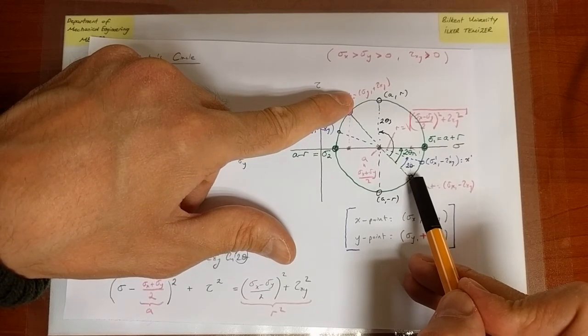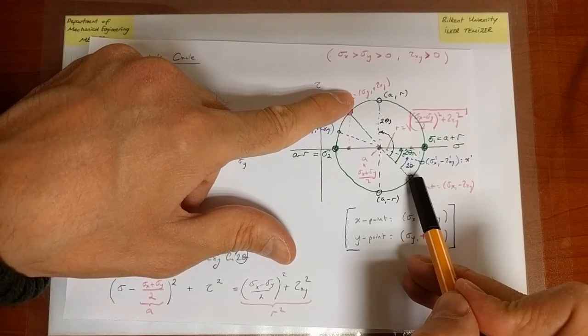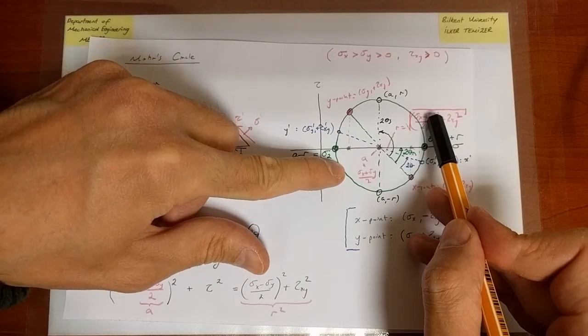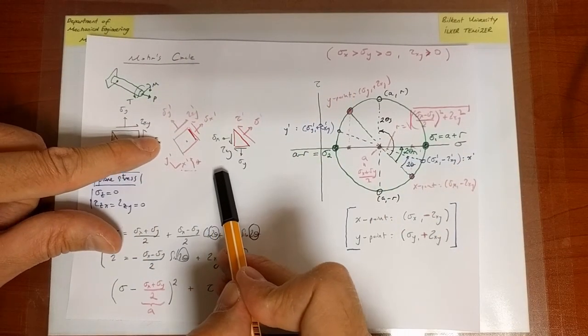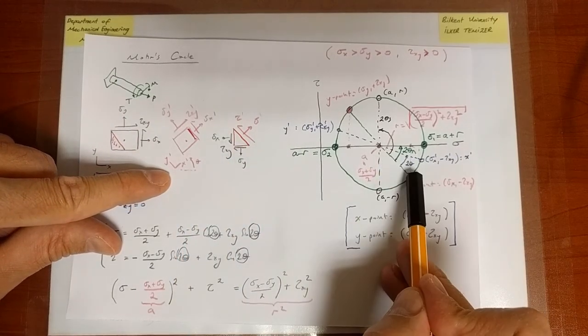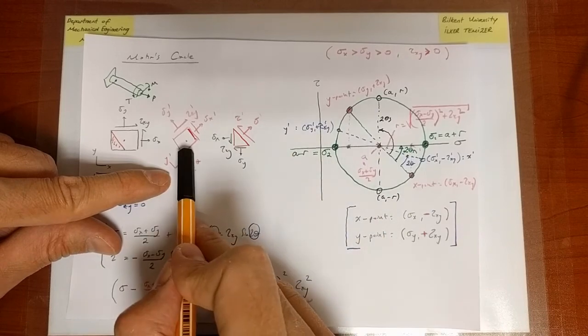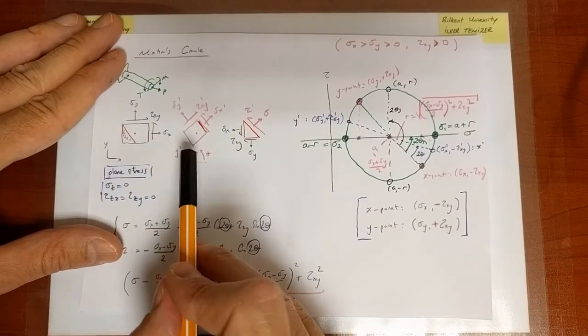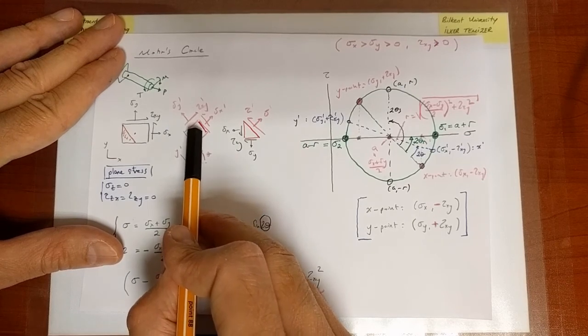it allows me to conclude that the direction of rotation on the Mohr circle is the same as direction of rotation on the physical system. Okay? It's just that the amount is twice as large as the physical system. Okay? And always, again, keep in mind, nothing is really rotating physically.